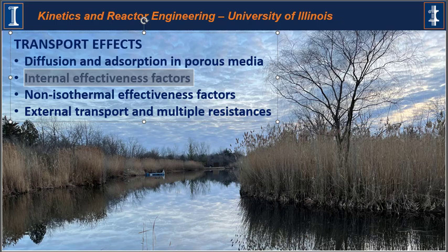However, the active catalyst material is usually dispersed on a high surface area porous support pellet, and in order to react, reactants must diffuse from the bulk through a boundary layer to the external surface of the pellet, and then diffuse through a pore network in the support, and then finally adsorb and react to form products at the active sites. Still, there's one more step: these must return to the bulk as products.